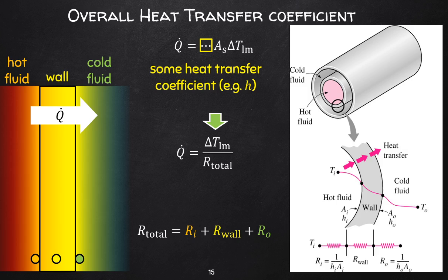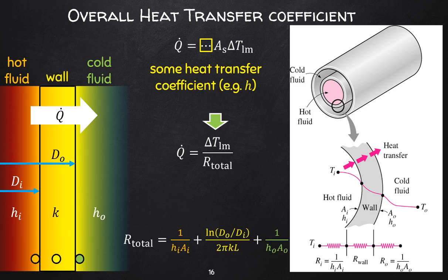Now the primary coefficient, because we are working with moving fluids used for this purpose, considers the resistance to flow, which would obviously now become more familiar for you guys, because we've been doing a lot of flow through pipes and things like that as well. Now recall that the resistances are made up of the convective heat transfer coefficients of the two fluids, as well as the thermal conductivity through the tube wall.